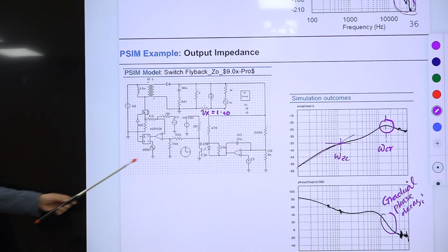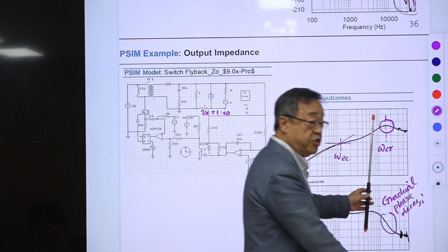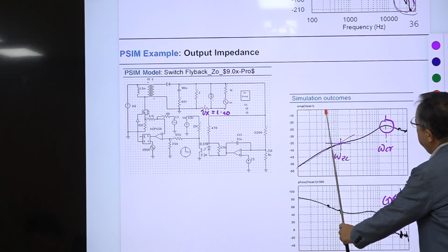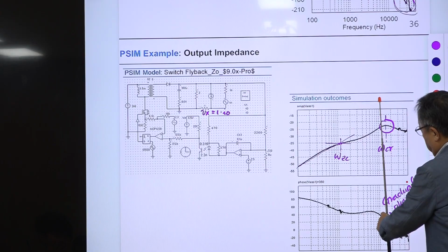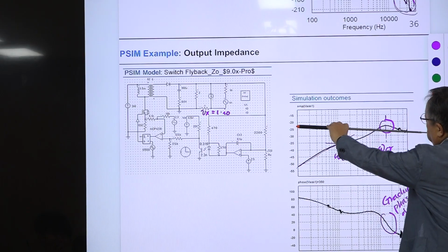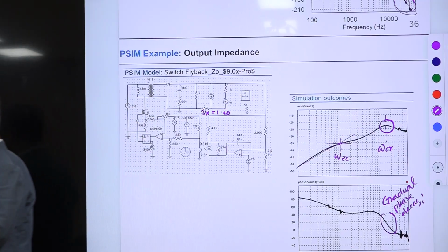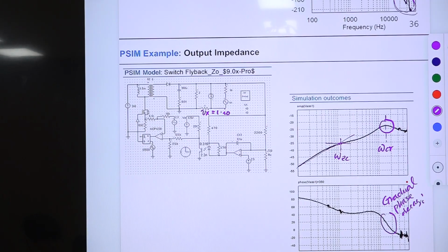If you have this second order feature, then what will you have in your time domain response? This second order is generating oscillatory behavior. So from this, there is a lot of information. This is related to the compensation zero, and this is the loop gain crossover frequency, and the magnitude of peaking is related to the oscillatory behavior of the time domain response, right?